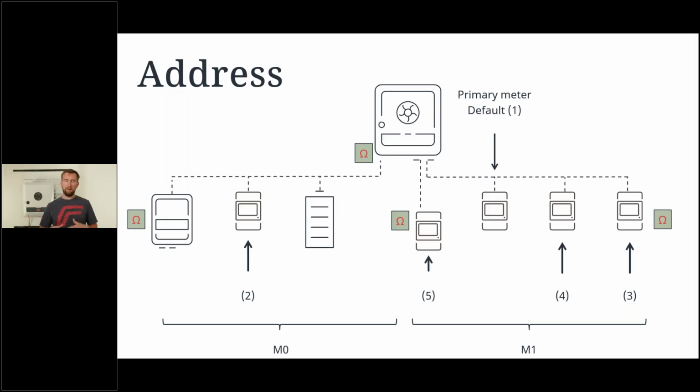Now, we have several Modbus addresses already predefined. So the OwnPilot has a predefined Modbus address. The battery has a predefined Modbus address. We don't have to worry about the inverter either. The only thing we're going to determine is different smart meters.